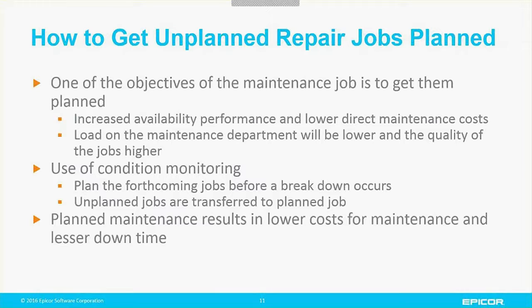So planning maintenance really can be quite simple. It can be the machine manufacturer's belief of what the service intervals should be, backed up by your own understanding and monitoring of those machines to evolve that through to a more precise level of service interval, or picking up various machine conditions and having that information then monitor drift, performance drift of various parameters, and extrapolate that through to when it's considered that maintenance is going to be required, not because the machine is broken down, but because it's continuing to drift, say, on a temperature profile or an energy draw.